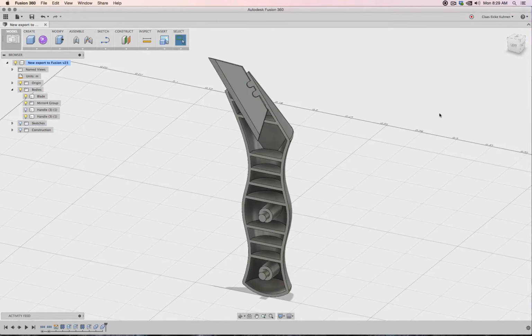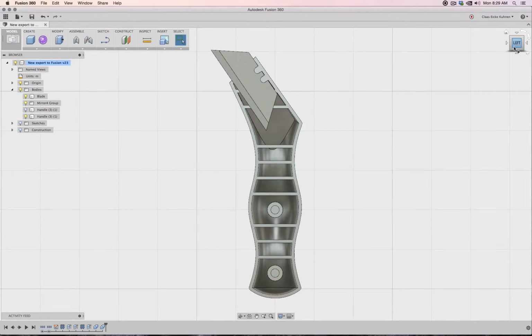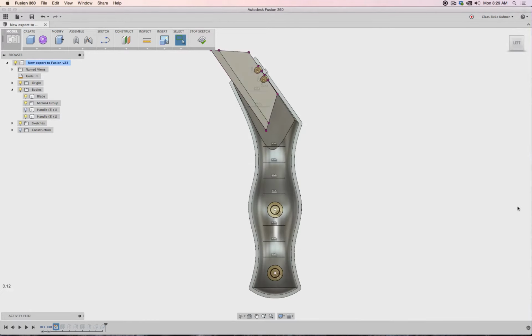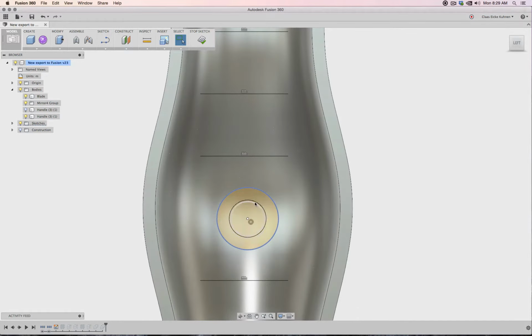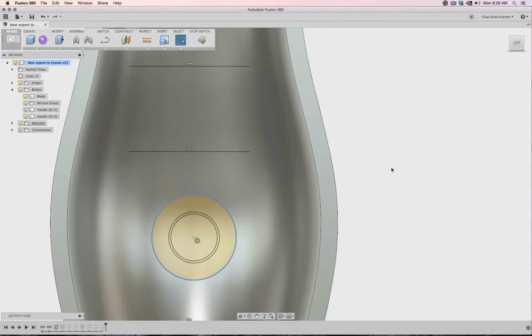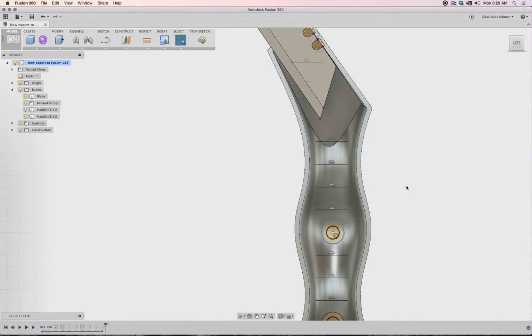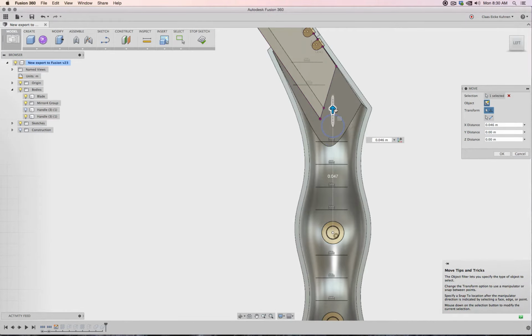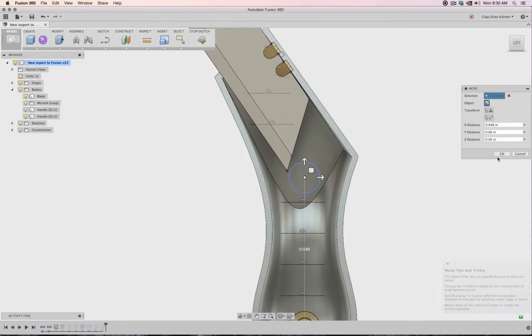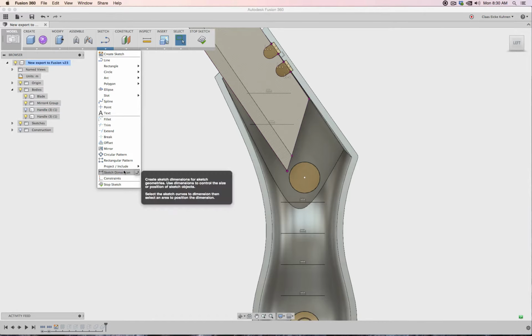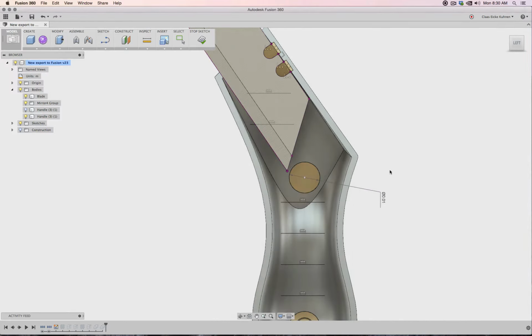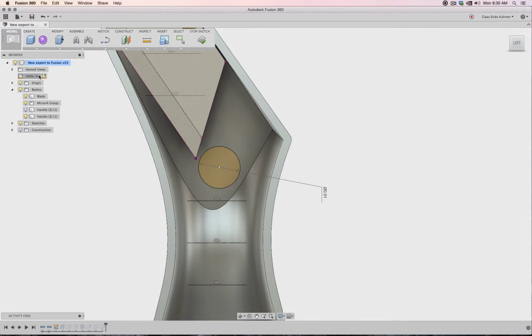Okay, so here, this sketch, for example, has the information about those rings. And what I'm going to do right now is pretty much very basic. So I'm going to create a copy and paste of this ring, move it straight up, maybe to there. Okay, and then on the inside, I would like to have, let me see what the dimension first is, forgot that one. Oh, I'm in meters right now. Let's go to millimeters, okay.